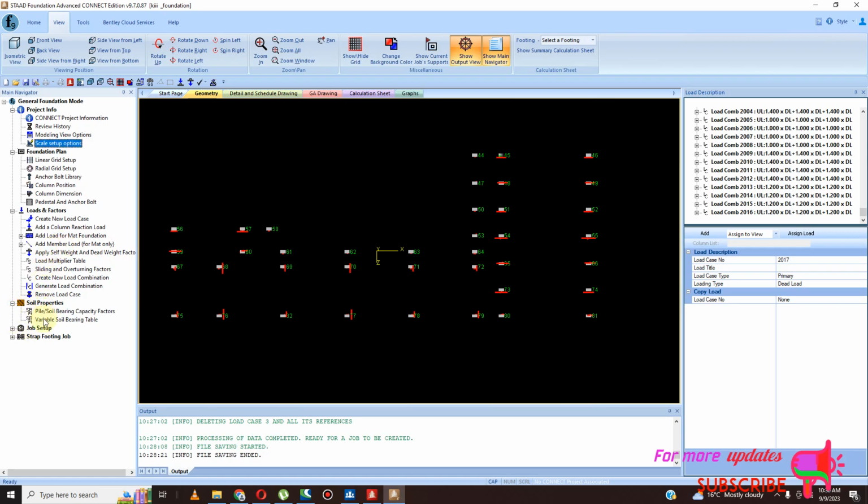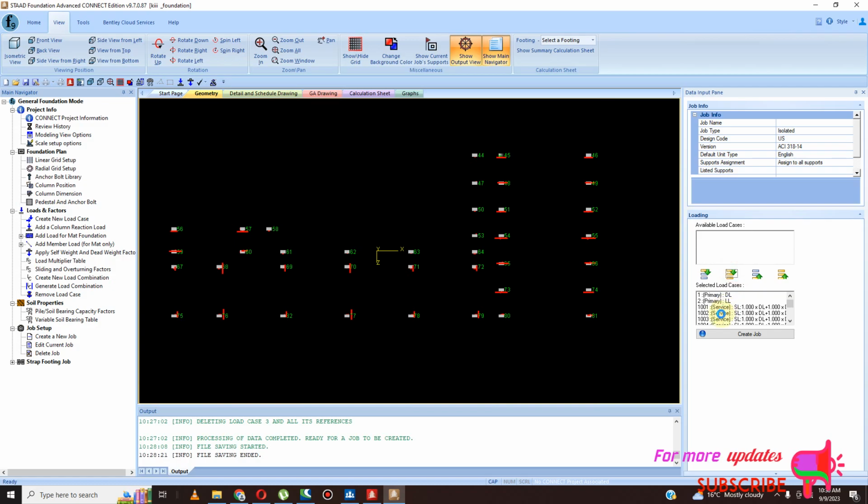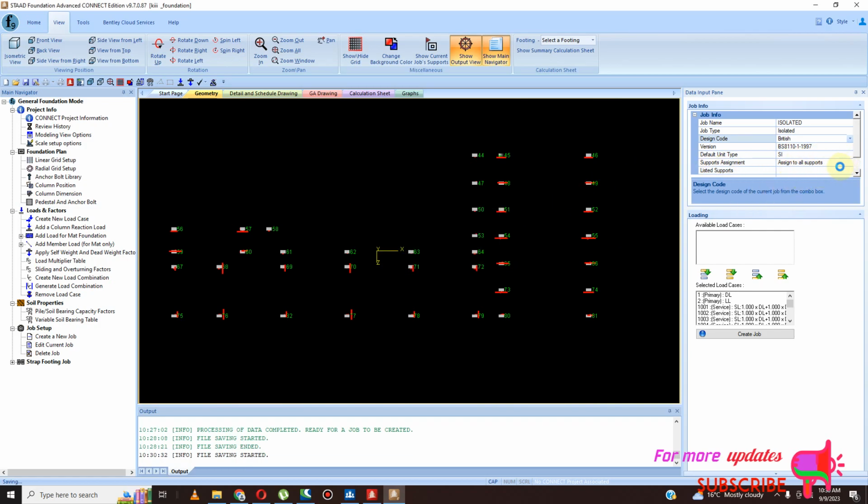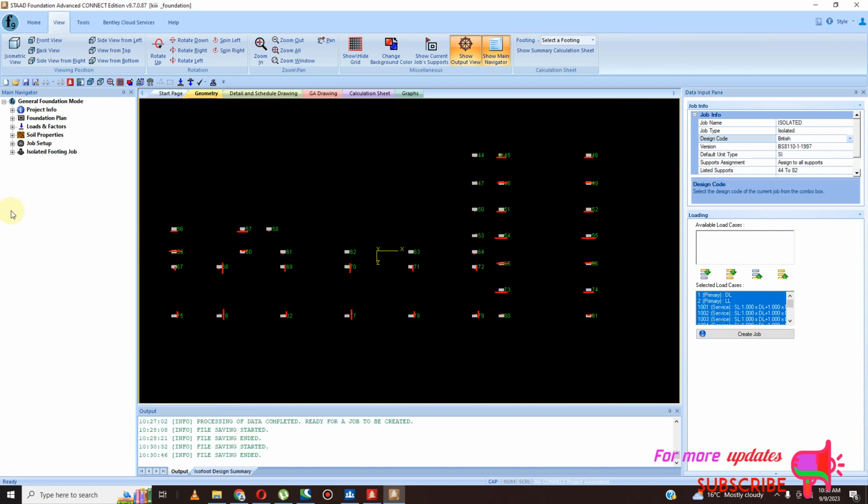So go to soil property, create job. The name of the job is isolated, type isolated. I'm going to use British. I assign to all supports. Then create job. Job has been created successfully. Then I go to my isolated footing job.